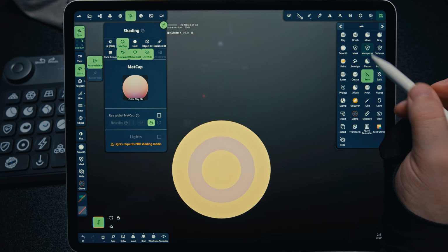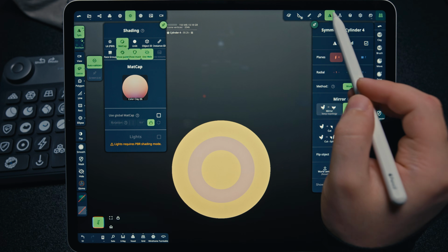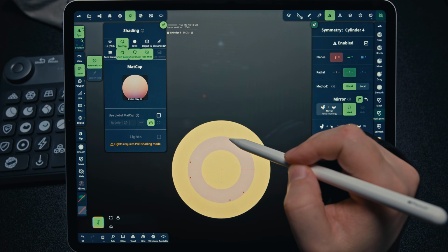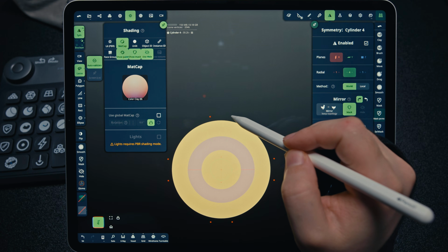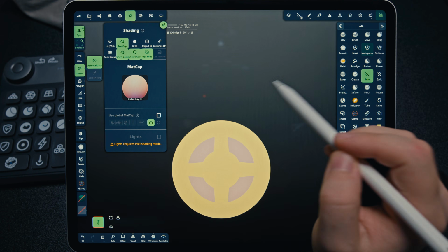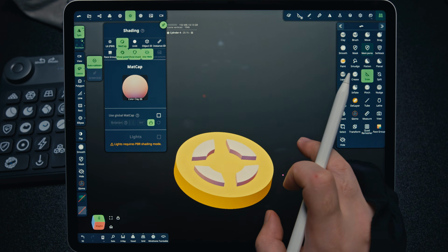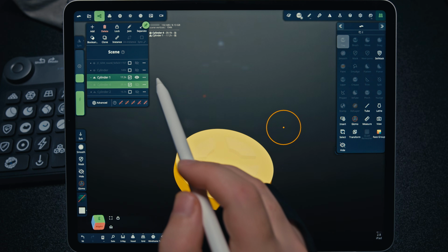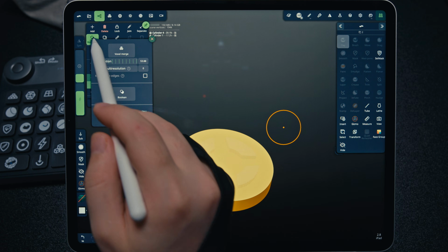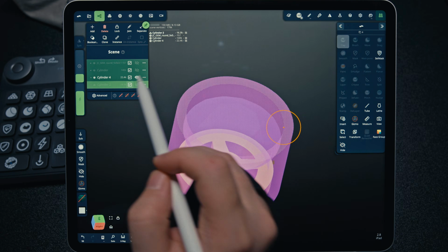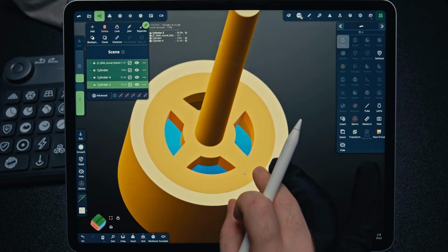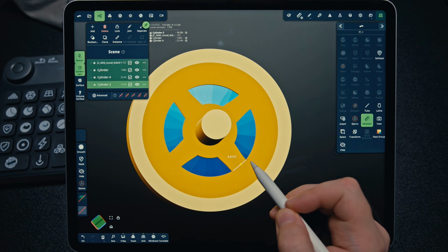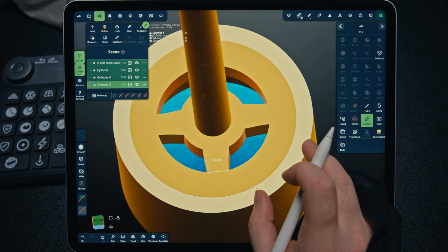Next, I will work with the trim tool, and first we need to turn on symmetry. I always try to find it visually. This looks right. I will trim it like this. Our task here is to leave enough metal, and I think this will be good. Next, let's boolean our plate with this element. I'll check this dimension. It's about 0.6mm. This is enough, so we can move on.